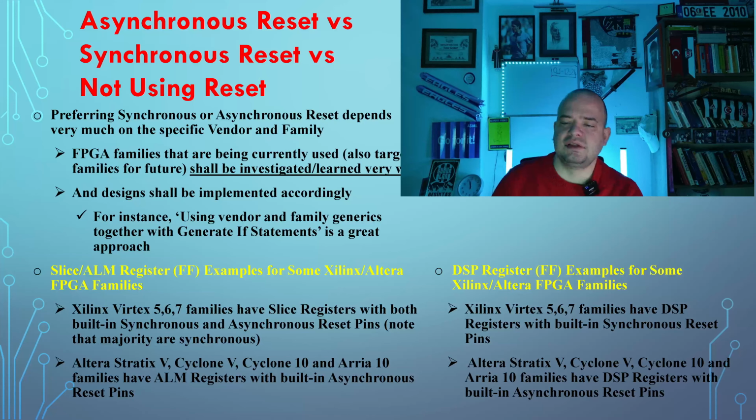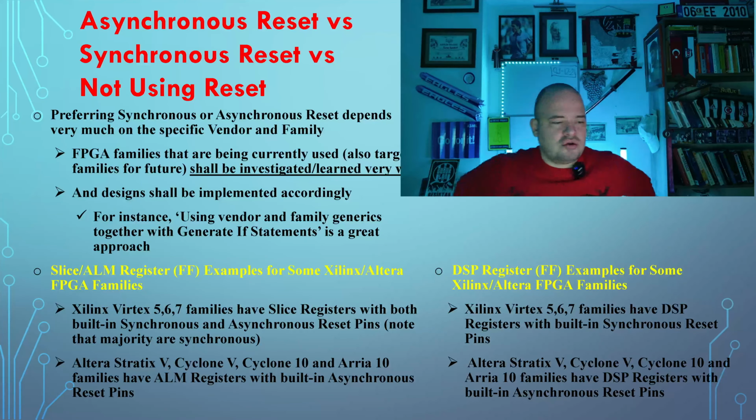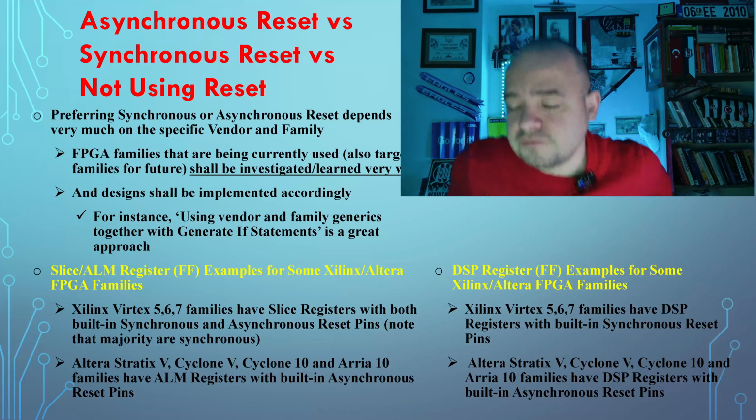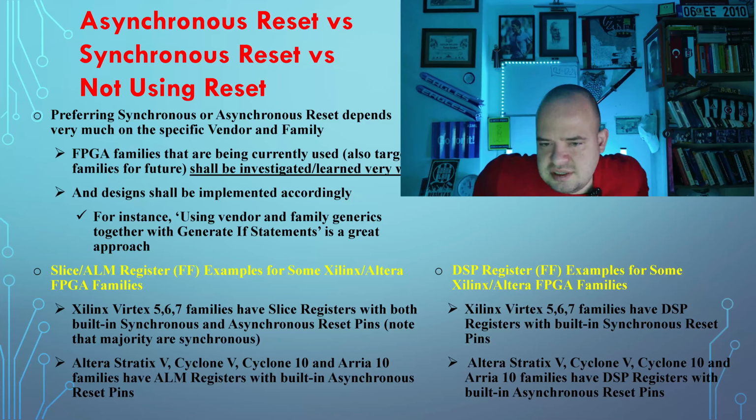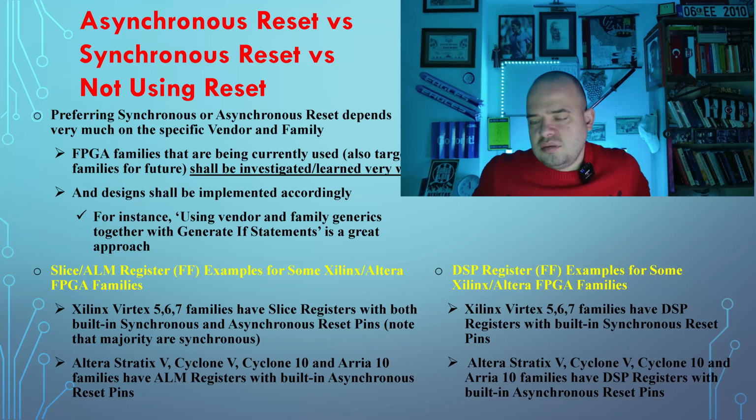Altera Stratix 5, Cyclone 5, Cyclone 10, Arria 10 families have DSP registers with built-in asynchronous reset pins. So then your optimization, your coding, is changing not only depending on the vendor, but also depending on the family as well.